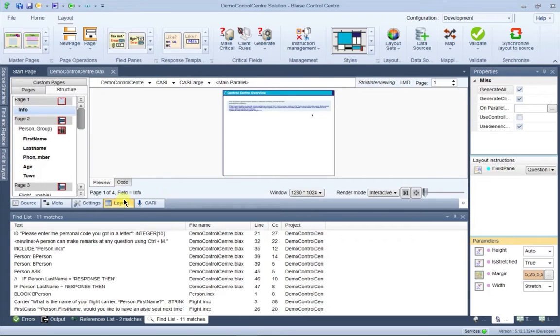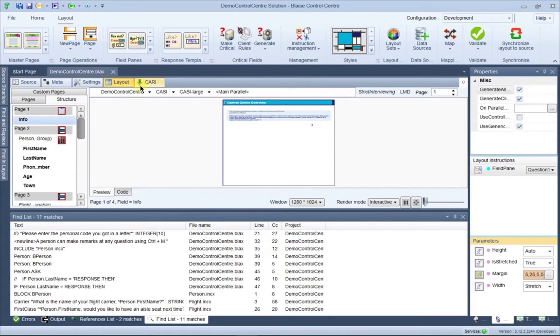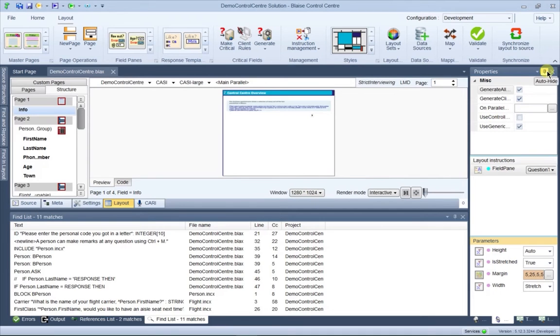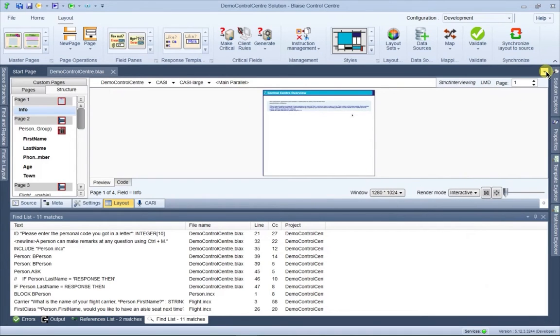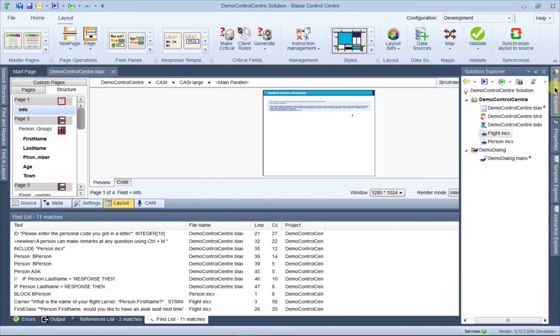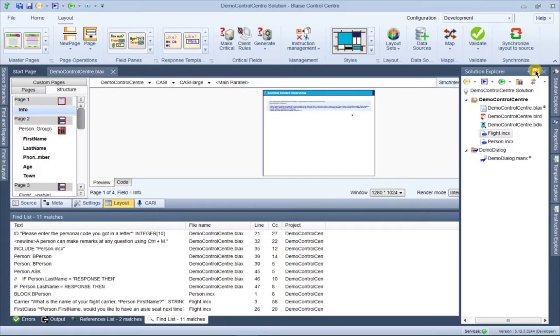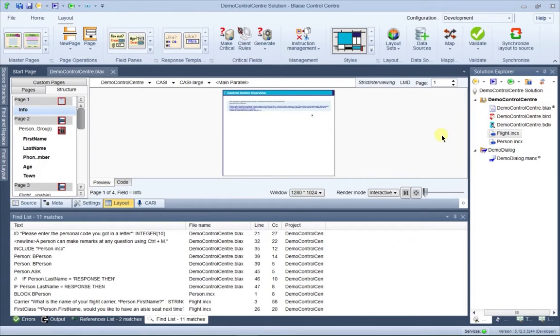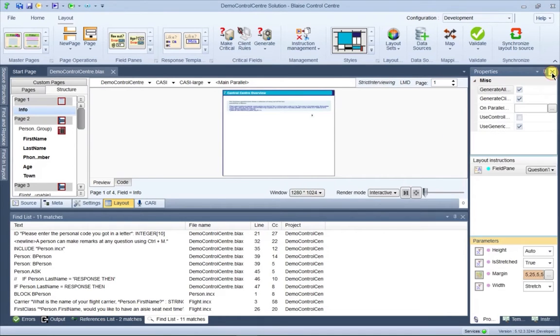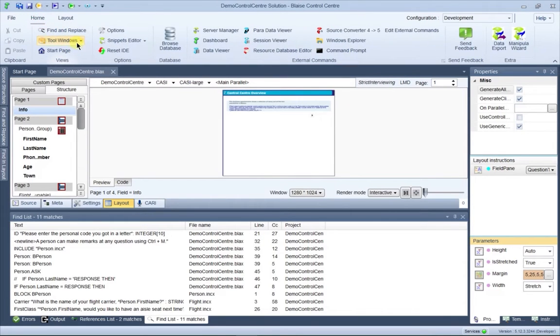If you prefer having the Views tab at the top of your main window, you can click on the icon on the right side of the Views bar. The Unpin icons on the right side of the panels will collapse a panel into a tab. You can hover over the tab to see the panel again and repin it. This is useful if you are working on a small screen or if you only want specific panels visible at all times. If you don't need one of the tools in the panels, you can close it altogether by clicking on the X. To reopen it, go to the Home ribbon and choose the tool from the Tool Windows drop-down.